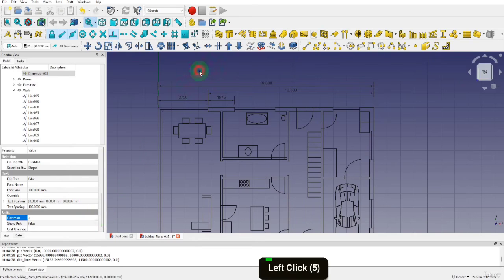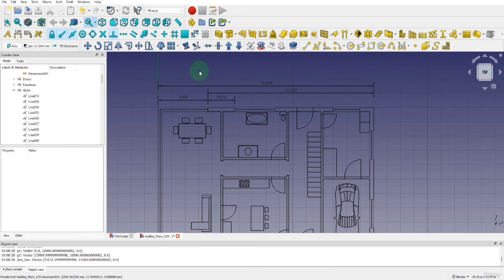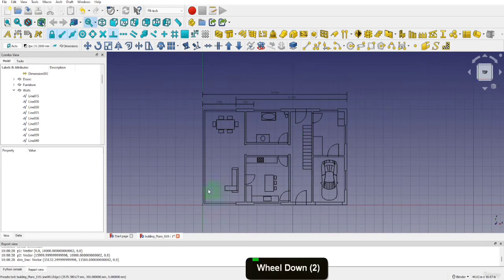I'm going to continue around and add in more dimensions around the drawing. Try work around and mark these in and also on the side. Adding dimensions along the vertical will be the same, just make sure and specify the x-axis whether positive or negative. When you do get those added, make sure and add the dimensions into the dimensions layer in the node tree.